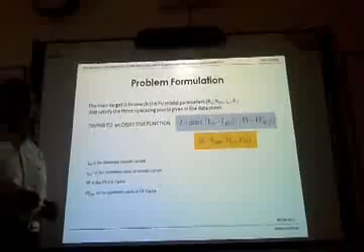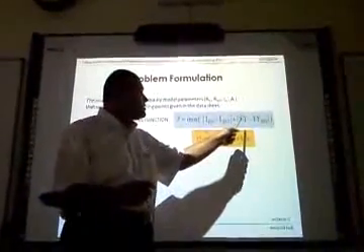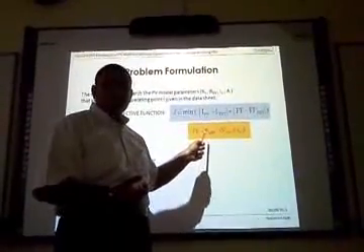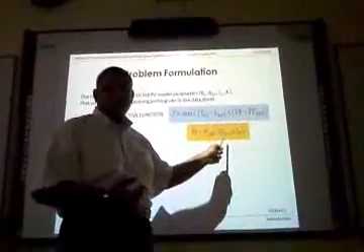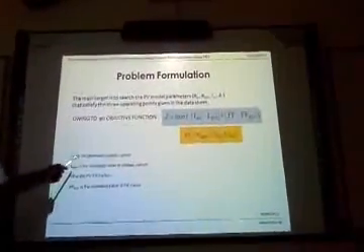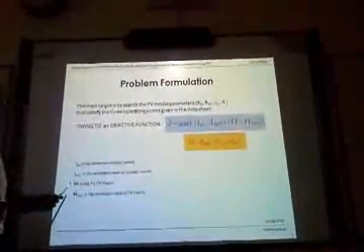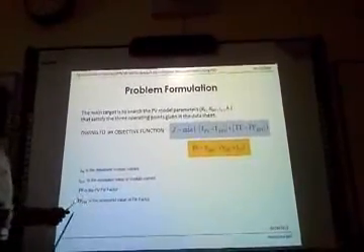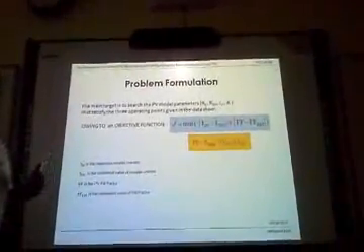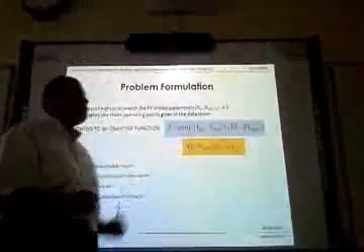In our work, the objective function is the difference between IPV minus I estimated plus the difference between fill factors. Fill factor is defined as P at maximum power point over the multiplication of open circuit voltage and the short circuit current. So, IPV is the datasheet module current, I estimated is the estimated value of module current, FF is the PV fill factor, and FF estimated is the estimated value of fill factor. So the main target is to estimate these values which can minimize this objective function.